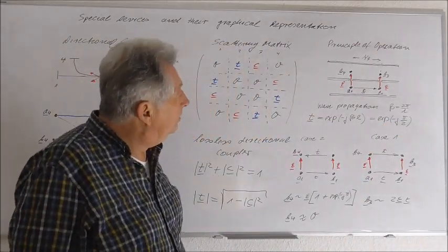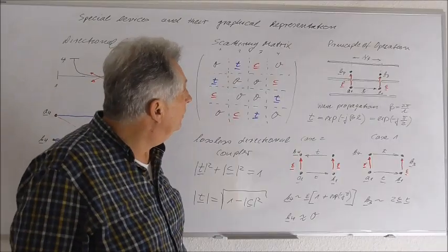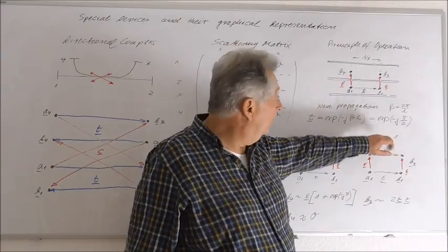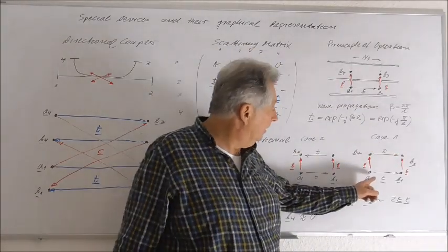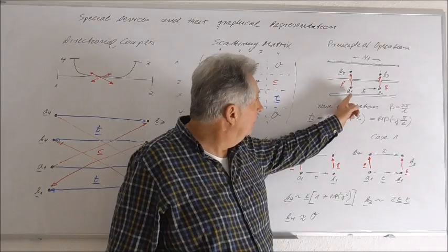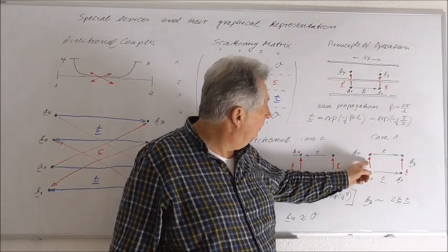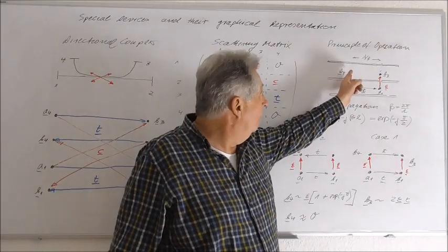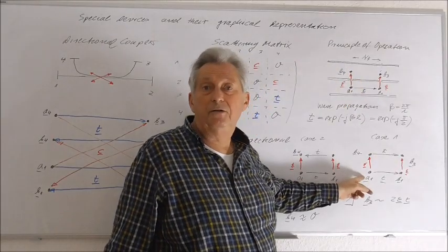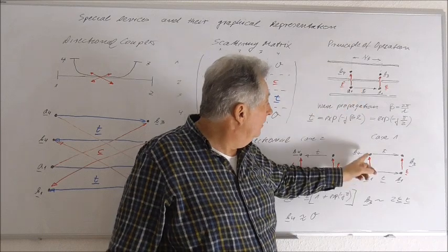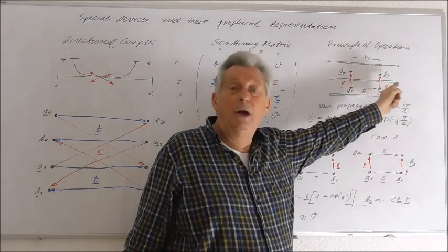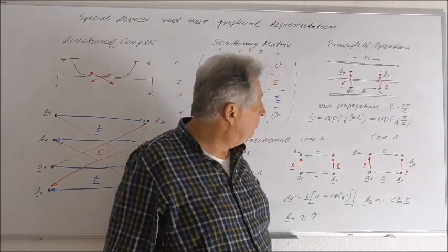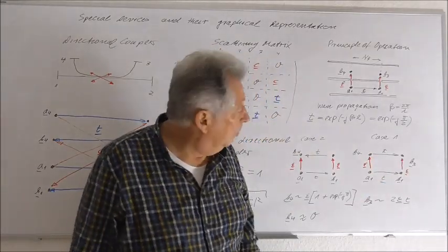And now we can, in principle, distinguish two different cases. First I want to discuss case 1. In case 1, I assume that I have a wave amplitude A1. Of course, part of the wave amplitude will be coupled into our waveguide, which I described by epsilon, and then in this case a wave will travel along this distance, and again here we will have t as a transmission factor, which is essentially 1.